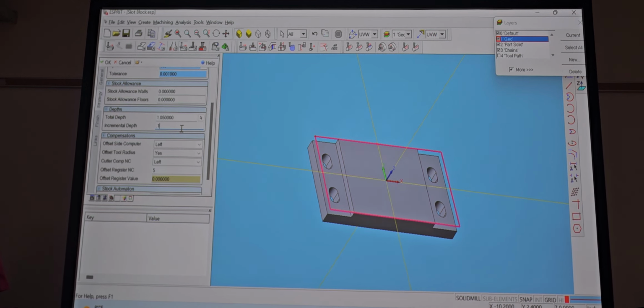Doesn't it have to be the same tool number? Exactly, right? That's going to be your D value. If you have a 5 there, but I'm using tool number 2, that's going to jack me up, right? So this is my tool number 2, so that has to be a number 2.